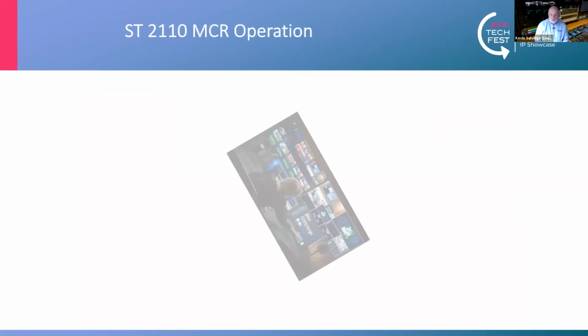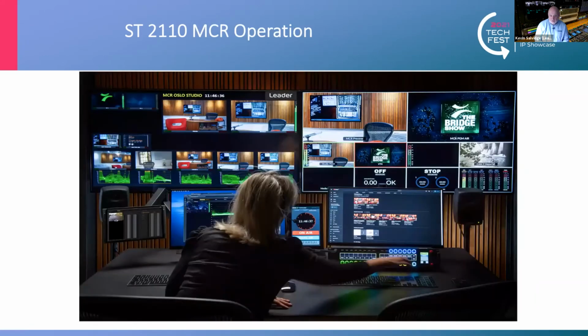And this can also work in a master control environment where you have the traditional instrument views for monitoring and analytics of the IP network and multi-viewer displays like you would do in an SDI world. And with the 440's NMOS integration, you can use NMOS router controllers to switch sources like you'd expect to do in an SDI world.